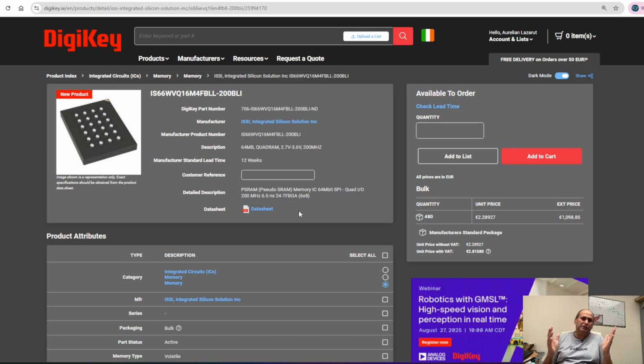So how does the refresh cycle work? If you don't access the memory and you have no refresh cycles, the information inside it will fade out. It will be lost. So they have internally a self-refresh mechanism. From time to time, they just refresh the memory. They make a fake access to those cells and they refresh. Now, if you have a system, and this comes to the architecture of the system, what your system does.